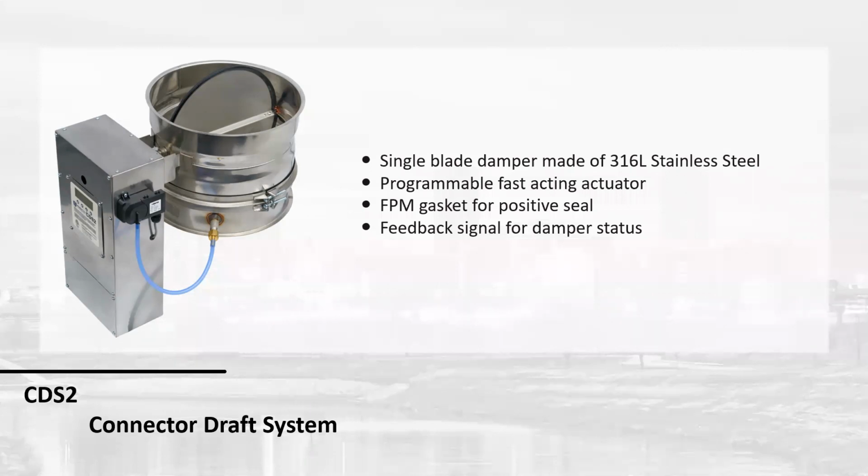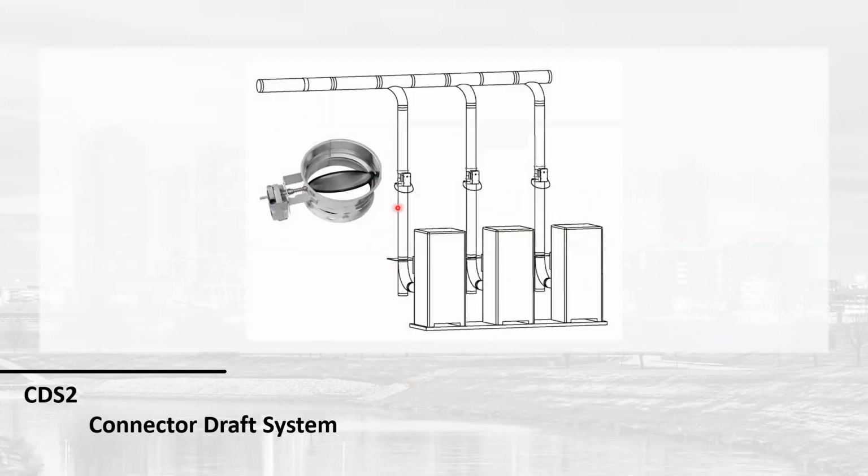So again, this has really allowed mechanical draft and mechanical venting to go to a whole other level. And the analogy I always use is it's like going from a full flow piping system to primary, secondary. Now I am going to maintain exactly the amount of the type of draft I need at each appliance. And I really don't care what's going on up here, so long as it allows me to maintain those pressures. Okay.